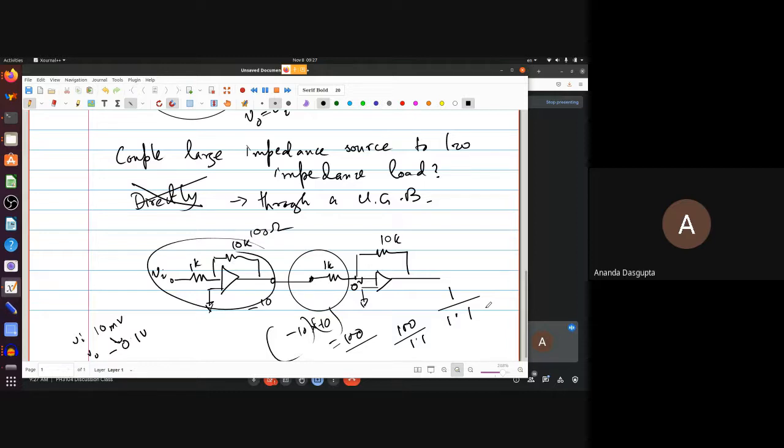But if you connect them, the second stage is going to draw current from the first stage, and that is actually going to change the current or voltage that is actually fed in. That could become quite a disastrous thing if you are using this to do precise calculations. Say, you want to guide an intercontinental ballistic missile using a real-time computer, using op-amps and stuff like that.